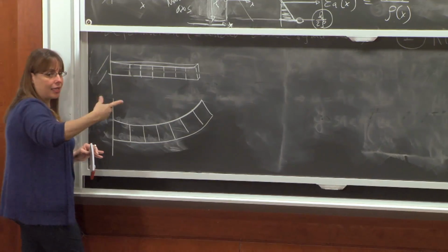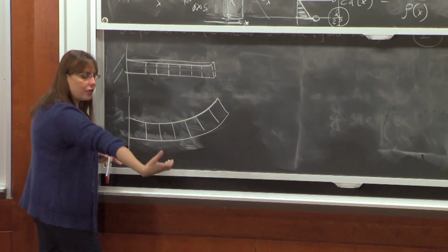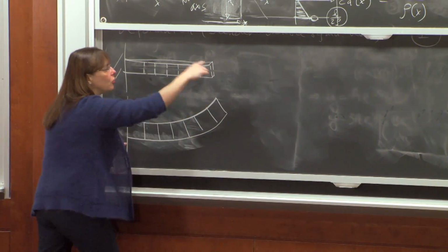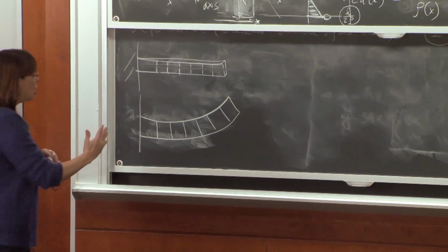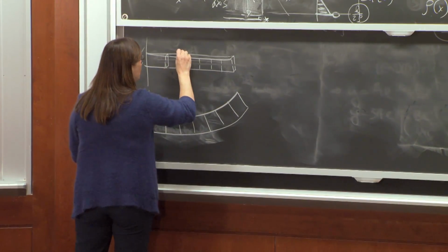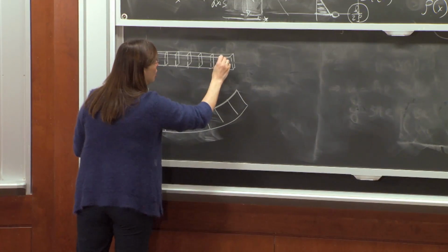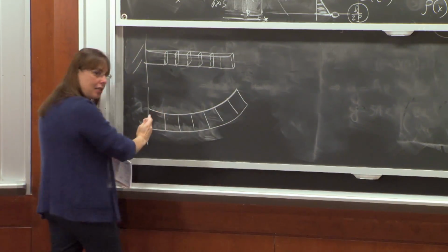And what that means is that each section rotates rigidly around now the z-axis, because now everything happens around the z-axis. In torsion, everything was rotating around x. Now in bending, everything rotates around the axis coming at you. You see? So each of these sections here, if I drew this section and this section and this section and so on, each of these sections still remains flat.